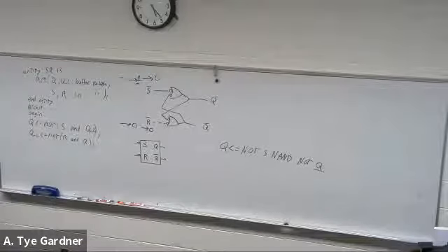Yeah. Do buffers, like if we wanted to simulate this, would the buffer basically still act like an out? It would be just fine. It would be driven. What a buffer means is that essentially it's holding on to that value and it is driving that value, but it's also waiting for a new thing to be written over it. So it's somewhere in between. It's just kind of like a holding spot. But there's the issue in simulation, which is actually a good question.